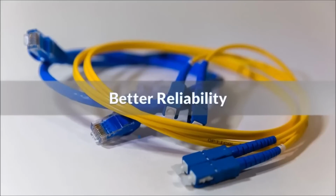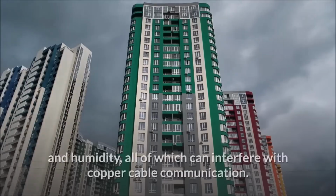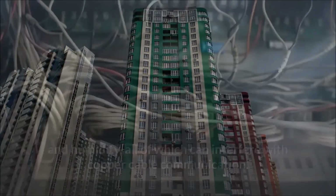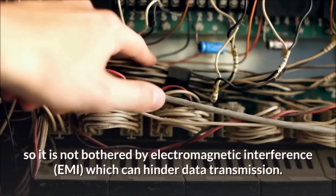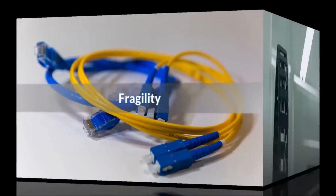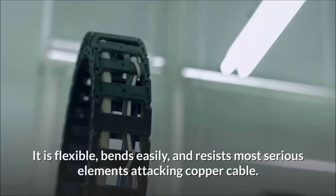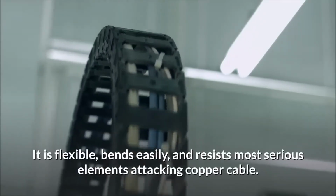Better reliability. Fiber is protected from temperature changes, extreme weather, and humidity, all of which can interfere with copper cable communication. Also, the fiber does not carry an electric current, so it is not bothered by electromagnetic interference, EMI, which can hinder data transmission. Flexibility. An optical fiber has more tensile strength than copper or steel fibers of the same diameter. It is flexible, bends easily, and resists most serious elements attacking copper cable.